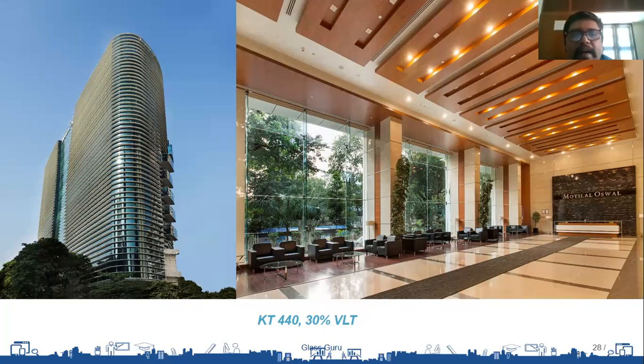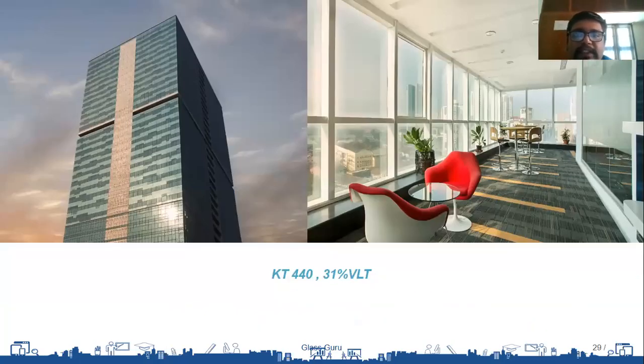If you have a look at the facade, this is one example. This is one more example. You can see that the space has a lot of white. In spite of having a coating done on tinted glass, it is not giving a green tinted look on the white. So it's just a misconception that whenever I go for a tinted glass, everything will look dull. In India, you can use a coating done on tinted glass, and you can still get an ample amount of light, provided you do the analysis and check whether it is sufficient or not.